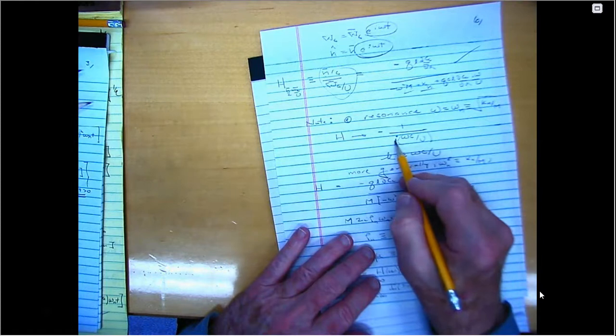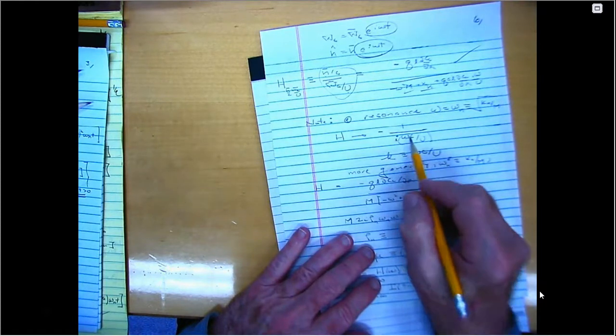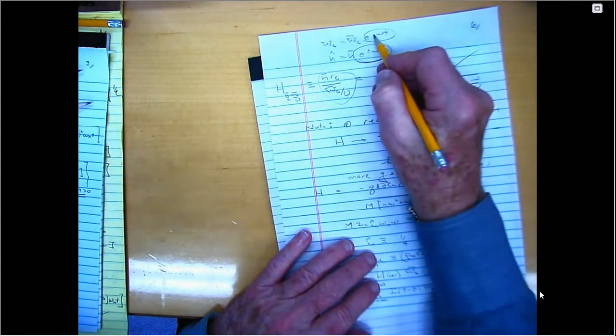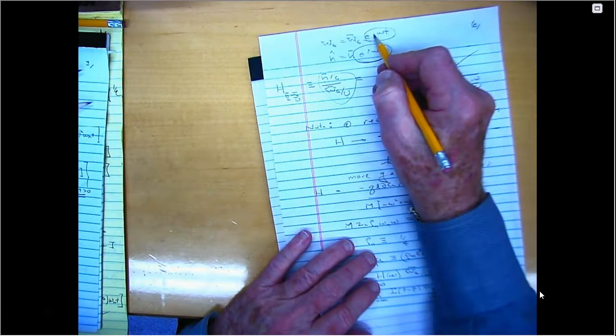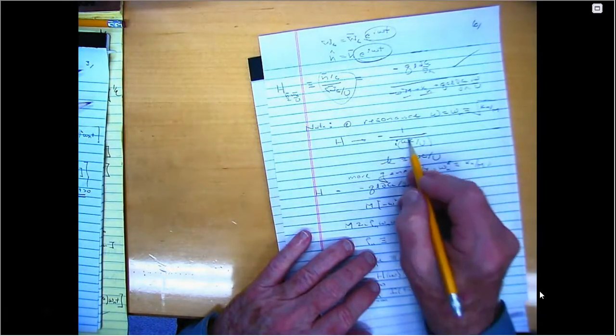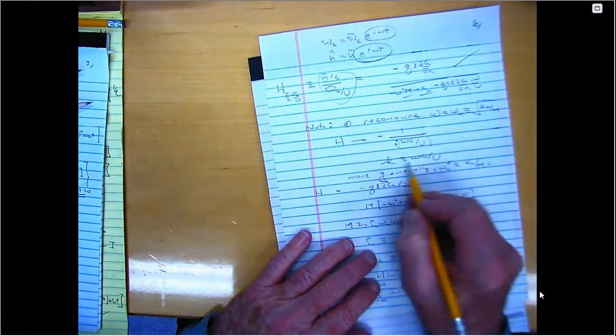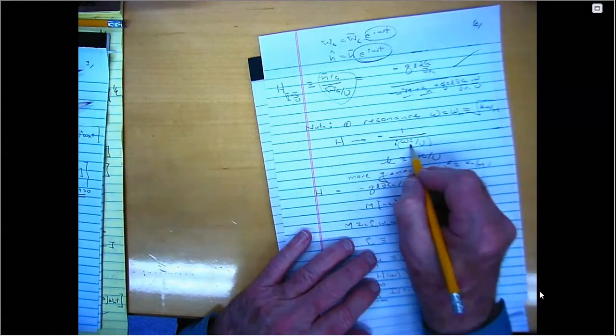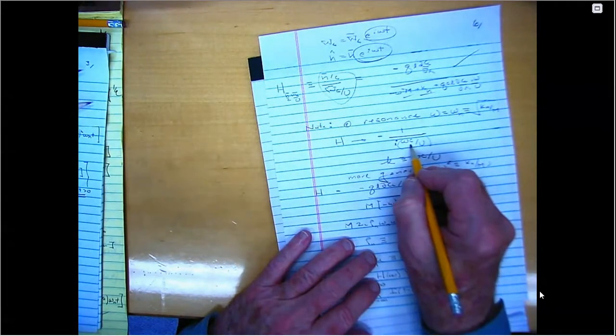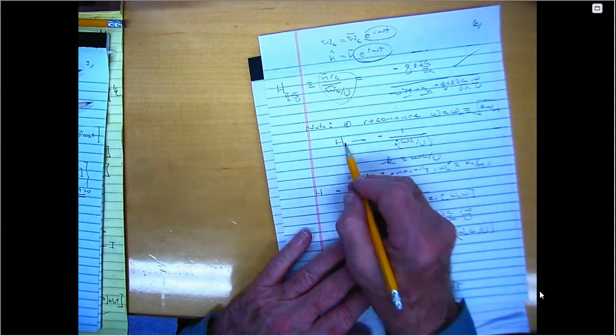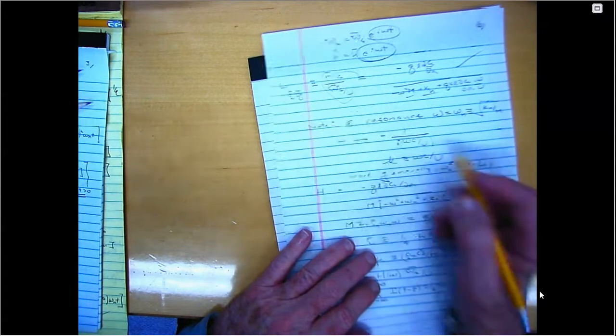Well, I have to say what i means in this case. By the way, this i is the square root of minus 1, the imaginary unit. Look, it's just 1 over omega c over U. And that appears so often that we're going to give it a name. We're going to call it the reduced frequency, or the Strouhal number or something. So this non-dimensional transfer function goes like 1 over the Strouhal number.